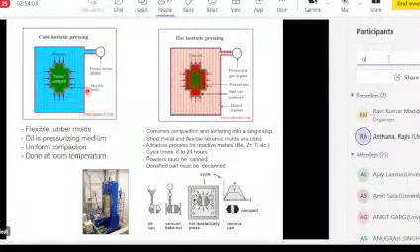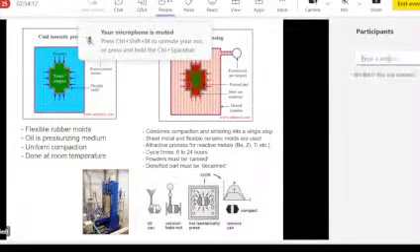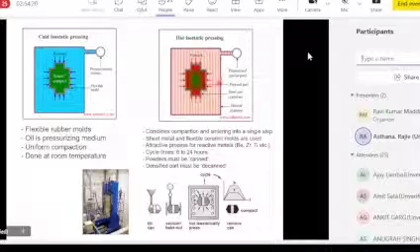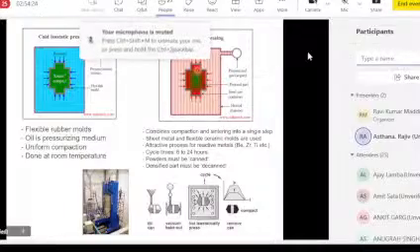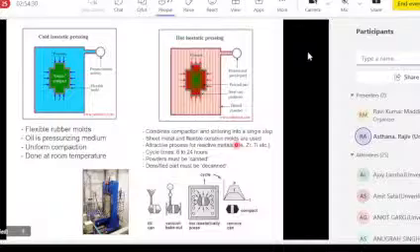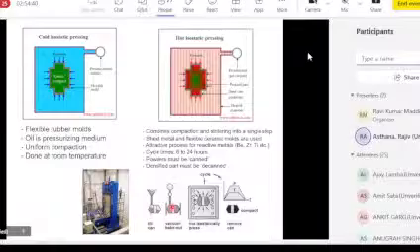Sometimes you do this process at high temperature. It's called hot isostatic pressing, which means you combine pressing and sintering into a single step. But to do that, you cannot use oil. Instead of oil as a pressurizing medium, we use argon gas. Inside this pressure chamber, you have heating elements that heat up the powders while they are pressed. You cannot use rubber molds as in cold isostatic pressing. So mostly people use sheet metal molds or flexible ceramic molds, which means you have to fill the flexible mold with the powders, de-air, and weld or seal the mold before you put it in this pressure vessel.